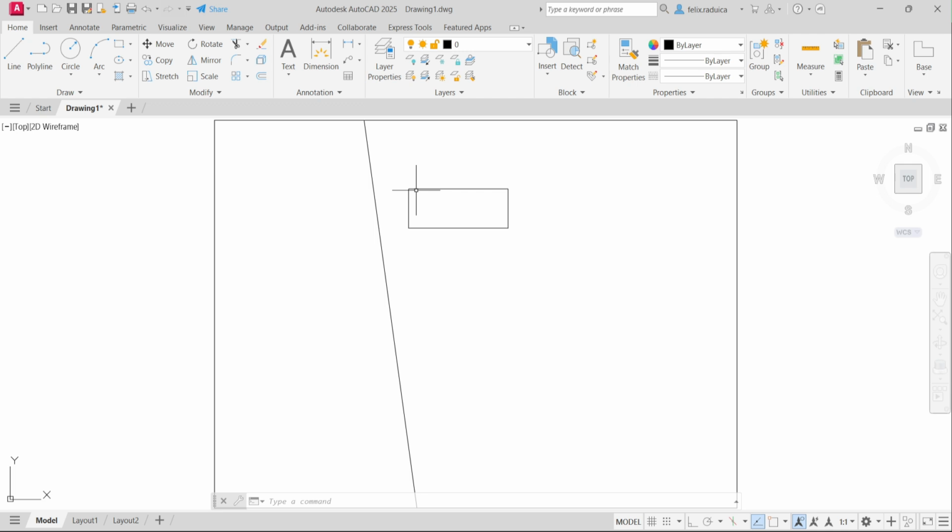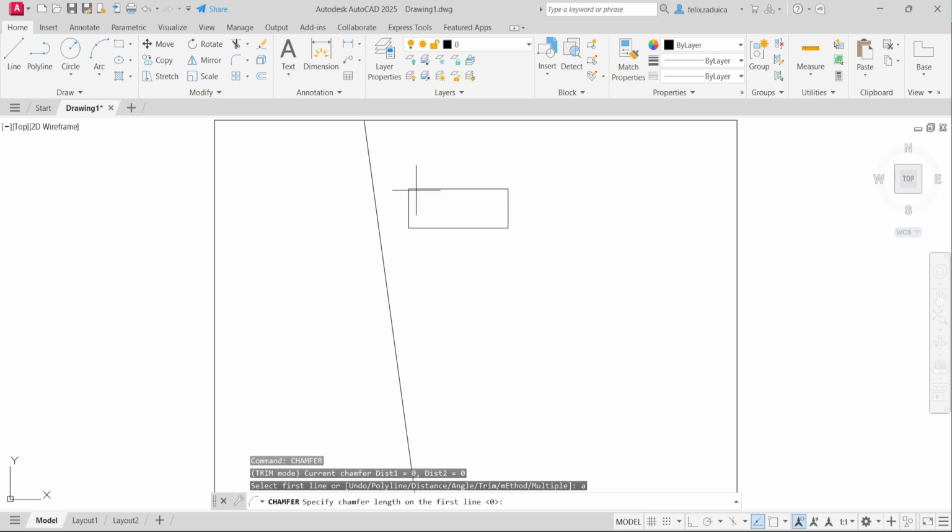So let's say I want to chamfer this corner at a 5 millimeters, 45 degree angle. So I'll type in the chamfer command, then I'll select angle, then I'll place the distance first, 5, tap enter, then 45 degrees and enter, and then select the edges that form the corner that I want to chamfer. This one and this one. And this is a chamfered edge.